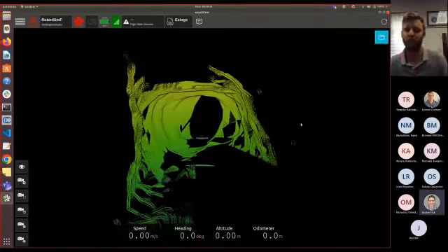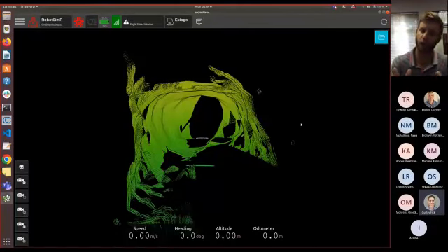Yes. So it needs approximately 3 meters by 3 meters in order to fly into the space. It's actually a little smaller than that. We just advertise that as 3 by 3, but it can typically fit closer to 2.7 meters by 2.7 meters. Of course, it's an algorithm. Essentially, those blue cubes I showed you, if a space was too small, the entire opening would be filled with blue cubes, and the robot would know that based on the safety features in place, it would not be able to enter that space safely, and it'll simply come back around and return home. So it needs to be approximately 3 by 3 meters in opening in order to enter.